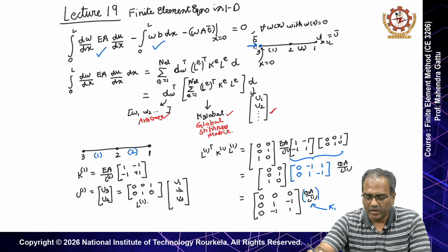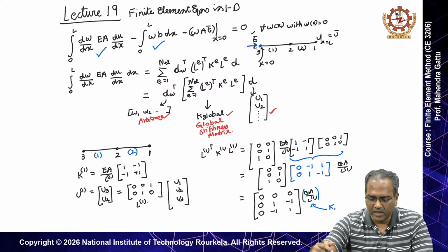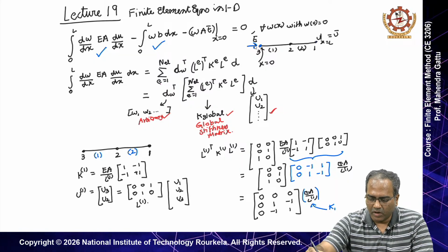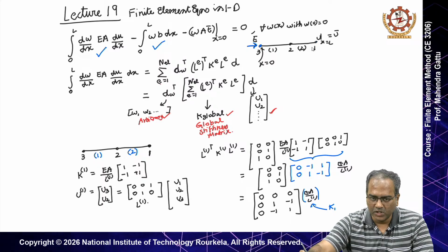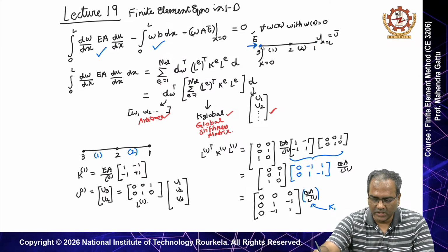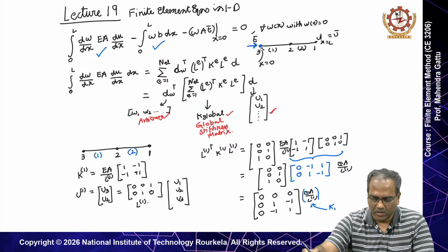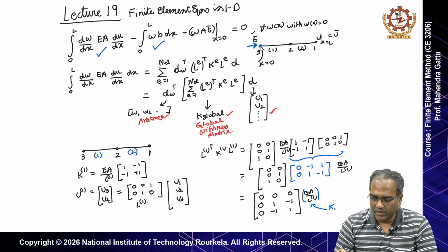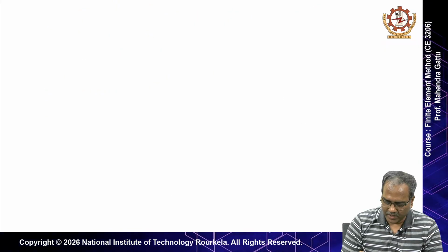It will again be a force vector with three rows, and the contribution will be at the third node only, and at node 2 and node 1 it should be 0, because traction is acting at node 3. So let us do that calculation for W A T bar at x equal to 0 using our shape function matrices.